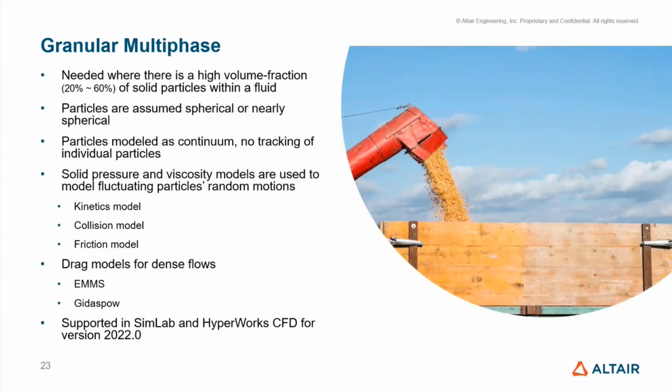So, in summary, granular multiphase is an extension of Euler-Euler multiphase and is needed when the volume fraction of dispersed solids is high, above 20%, within a carrier fluid. Particles are modeled as a continuum and assumed to be spherical or approximately spherical.